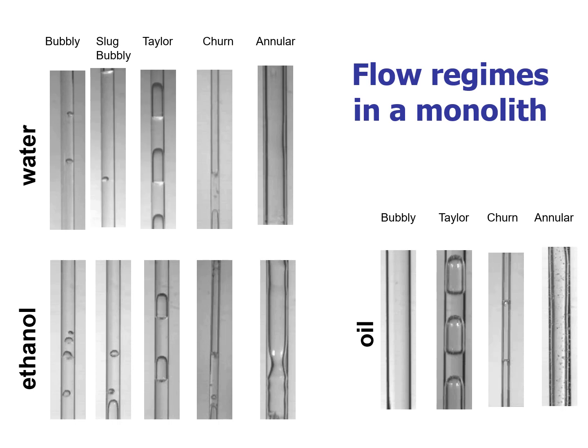For a well-defined set of conditions, we have the bubble train flow with the length of the bubble equal to or longer than the diameter of the channel, and the distance of separation between two bubbles is practically the same. It's flattened at the bottom and hemispherical at the top. This is the bubble train or Taylor flow.